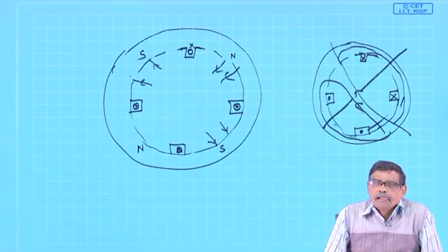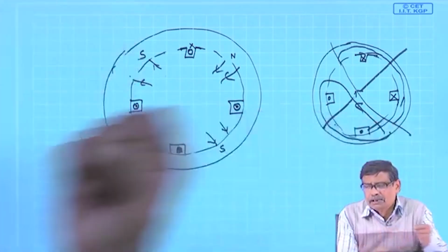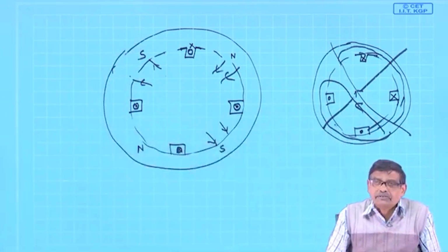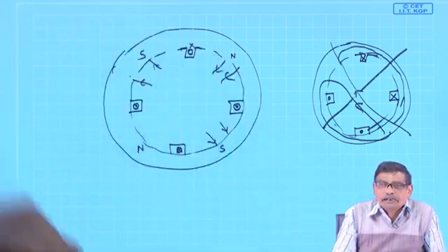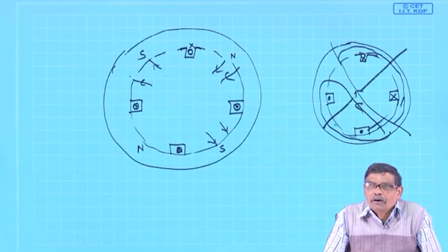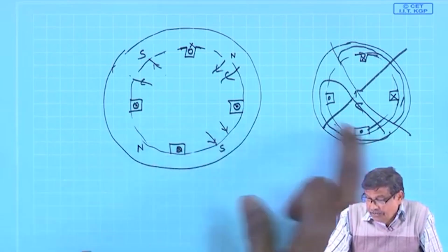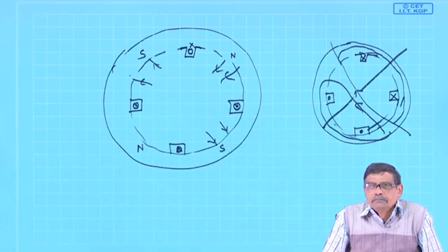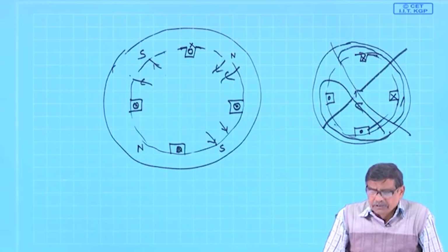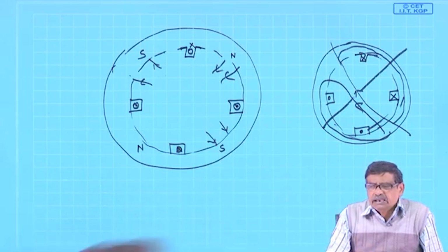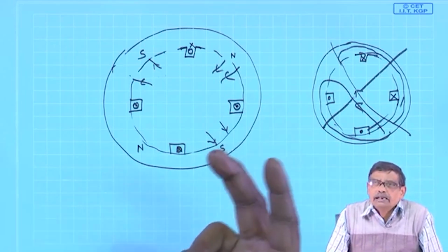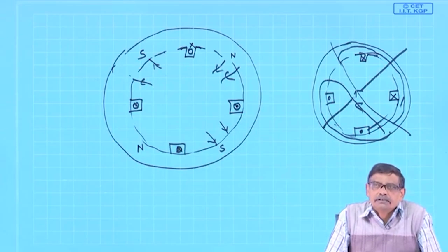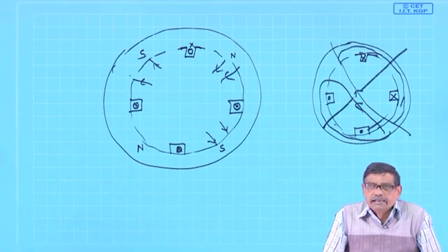But obviously, so many terminals you have to bring out from the machine, not simply 2 terminals for R phase, 2 for Y phase or 2 for B phase. To carry out this kind of operation, you require many terminals to be brought out, maybe from the groups of a particular phase. So, it was cumbersome that way, and you have to change that interconnection only to get 2 levels of speed, that is all, and having of course a cage rotor.